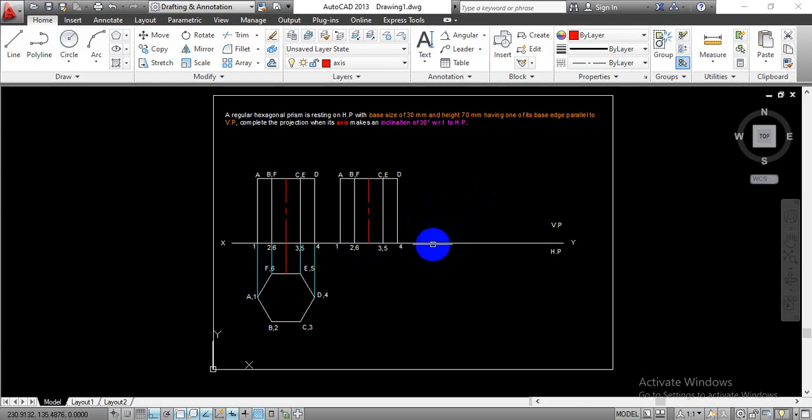We can form one triangle there, and as we know this axis is perpendicular to the baseline, this axis is at a 30-degree angle, this will be 90 degrees, and the remaining angle will be 60. So this base we can tilt at an angle of 60 degrees with respect to this corner point 4, so that we have the axis inclination of 30 degrees by default.